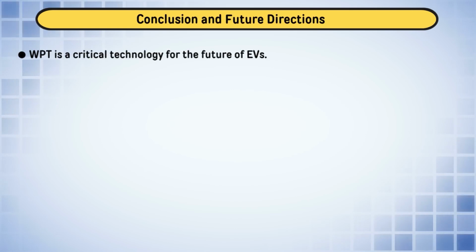And then, for performance under charging and discharging, we have achieved various parameter variations during dynamic conditions when mode transfer is taking place during charging and discharging. So, we have also operated this converter under dynamic conditions when we are switching the vehicle battery from charging to discharging and discharging to charging. Parameter variation during dynamic conditions, SOC is varied, and then mode switching from constant current to constant voltage. So, dynamic behavior in transition from CC to CV is achieved in this particular application.